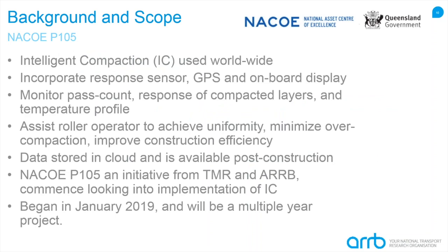A bit of background: I'm sure a lot of the attendees are already aware of IC, but in short, intelligent compaction, or IC, is not a new technology. It has been used worldwide for at least the last 15 years. What it does is incorporate response sensors, a survey grade GPS, and an onboard display on the common roller compactors that we use on construction sites. With this technology fitted, it gives us, for example, a pass count of our rollers and the response of the compacted layers. For asphalt applications, we also monitor the temperature profile, which is essential when we are compacting asphalt materials.